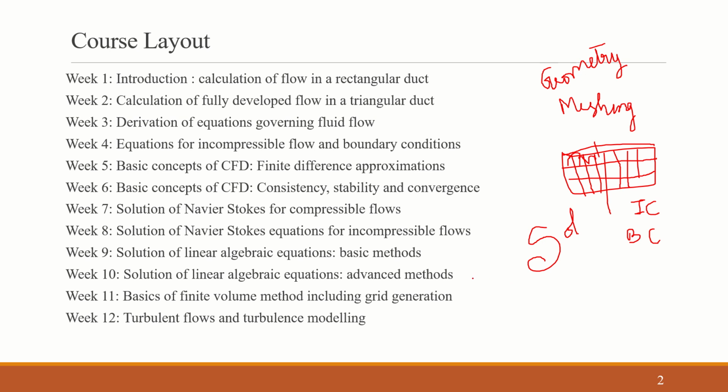Like we are solving these Navier-Stokes equations and getting the values of fluid motion if it is occurring, and also we know the position of the fluid in the next cells, and values like velocity, temperature if we are dealing with it, all those things we will get. And after getting all those values, we will analyze and say whether it is right or wrong. Most of the time, actually, I remember a professor of mine once told me CFD will not always give the right solution at the first moment itself. It will give solutions and they should be meaningful.